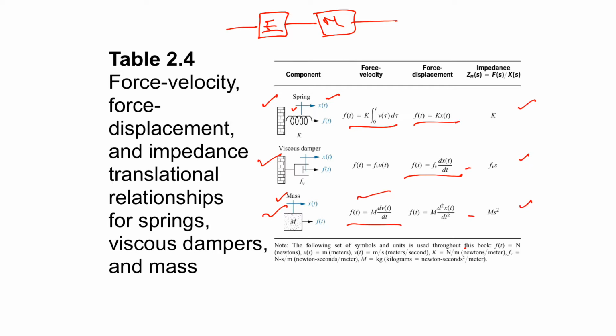These two energy storage elements, the spring and the mass, are analogous to the electrical storage elements, the inductor and the capacitor, and the energy dissipator is analogous to electrical resistance.